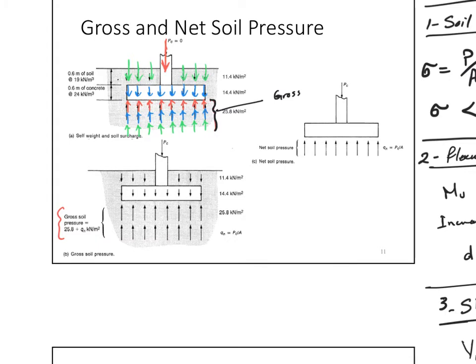Now, if I look at which ones will cancel each other at the footing outside the column, I will see that those guys will cancel those, in terms of finding straining actions on the footing itself. So to find the shear and the moment on the footing sections, I will only consider the red one, and the red one is the net.